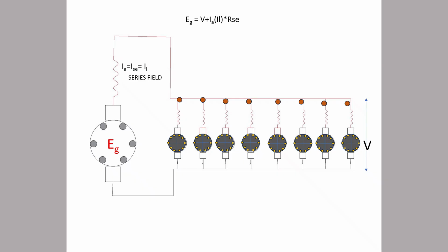In electric locomotives we use the DC series motor, as it has good starting torque. But nowadays we have replaced it with the three-phase induction motor with IGBT and GTO, that is insulated gate bipolar transistor and gate turn-off. The electronic system has come, and the control is through variable voltage, variable frequency.